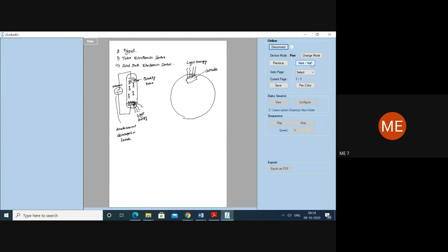Now, as I said, because of the presence of the light, electrons are going to be liberated from here. In the previous case, what was the problem? The liberated electrons move towards the negatively charged anode. If I keep the same structure, the problem which occurred in the previous case will occur here also in the second method. But here, we are going to place something called the dynode.